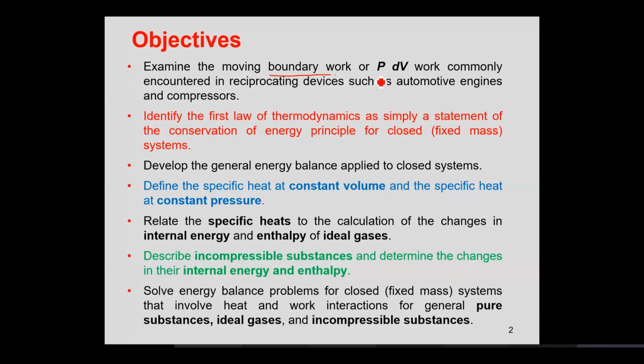Boundary work is normally recognized as PdV work, and this work is normally encountered in reciprocating devices, which are automotive engines and compressors. So the first thing that we'll do is assess the boundary work. Then we'll analyze the first law of thermodynamics, which is the conservation of energy principle for closed systems. We'll apply this law and develop balance equations for closed systems.